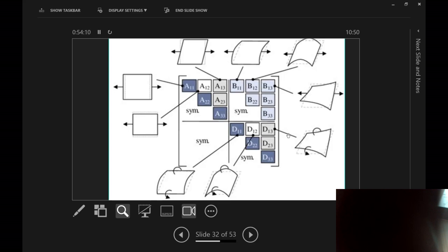A22, you pull it apart, it shrinks in the perpendicular direction. A33, through the thickness. If you've got A13, depending on the stacking sequence you have, you will have different behavior. I'll take you through it. A13, you extend it, but you can see it is shearing out. Can you see above?